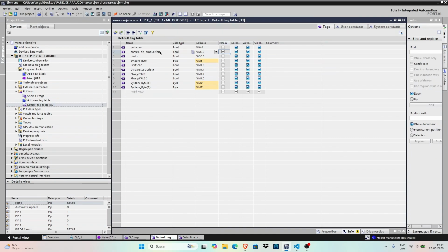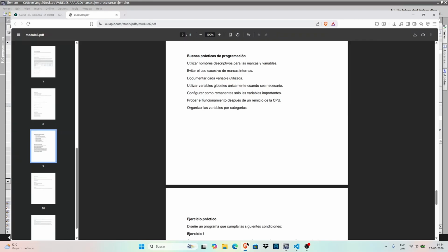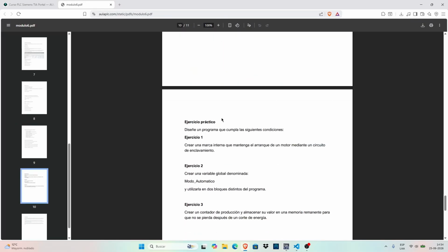They have to use descriptive names, because it will help you later. You know if there is a fault in the connection, you have to fix something. If they do not have descriptive names, they will not know exactly what the variable is. For example, engine. And they have 15 engines. And they only have the engine in it. Come on, they're not going to know what engine they're talking about, so they have to put engine 4. And thus they put the tag of the physical engine. You have to see there.